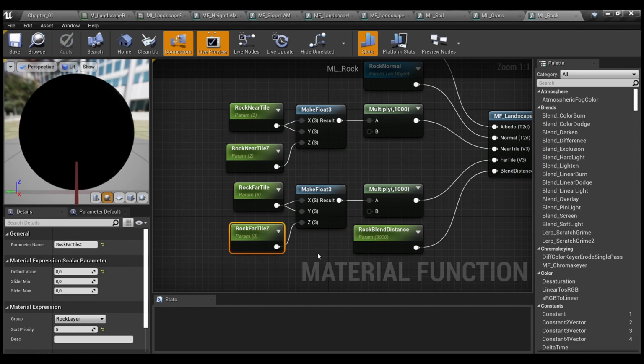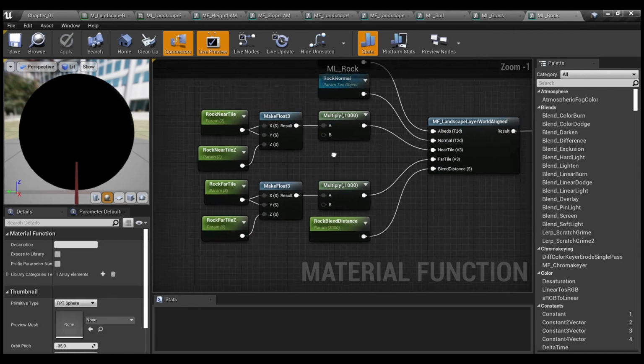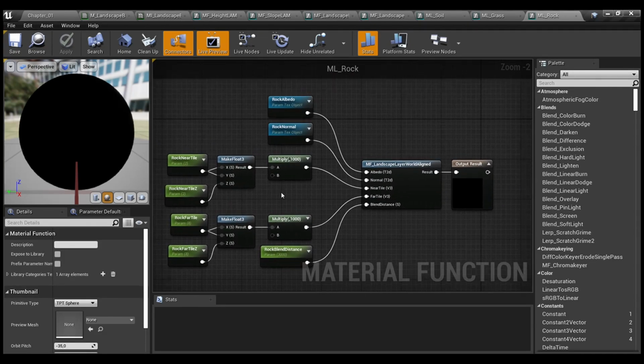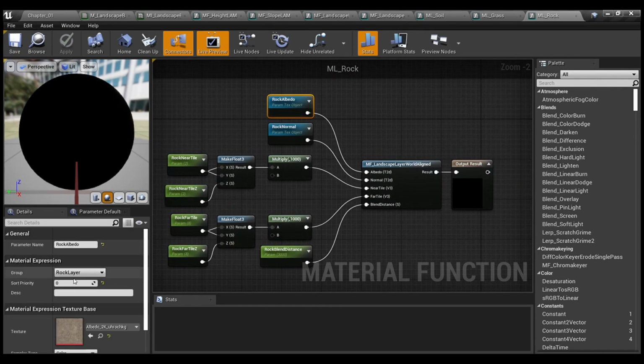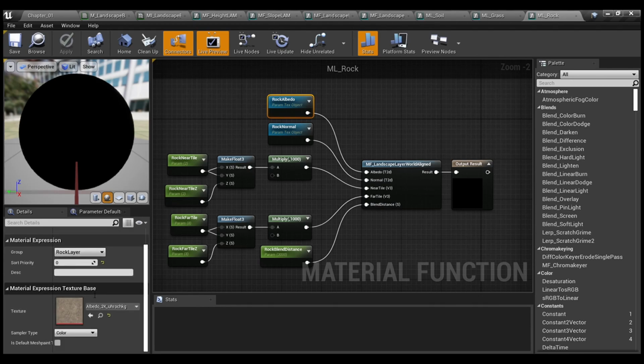So it's, as I said, for the sake of, if you don't like the tiling on your vertical slope, you can adjust it and it will be tiled more precisely. Also make sure that, as I said, base and normal samplers are set here. Don't forget.